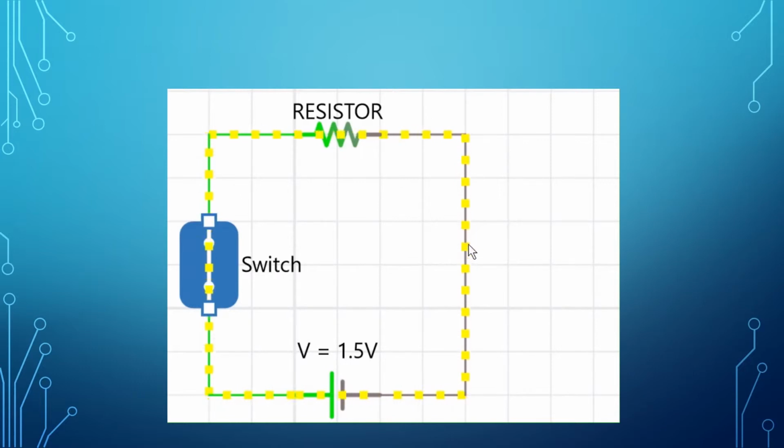I'm going to measure the current with an ammeter that I can plug in line in here. This will be in series. An ammeter will be in series, and it can be placed anywhere in this circuit. And it will measure exactly the same thing, which I can show you here too, no matter where we put it, as long as it's in series with our load and our source voltage. Okay? So the switch is closed, the resistor is resisting, and the voltage is volting.